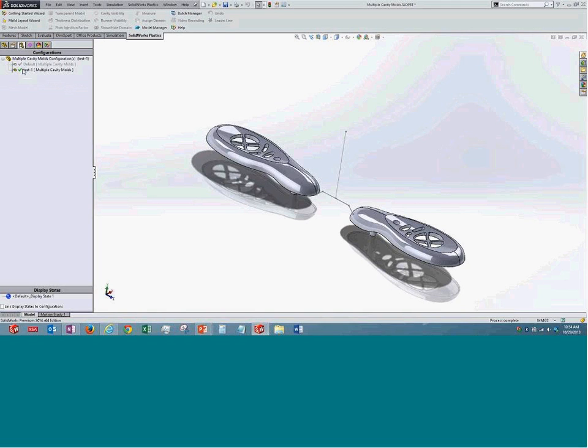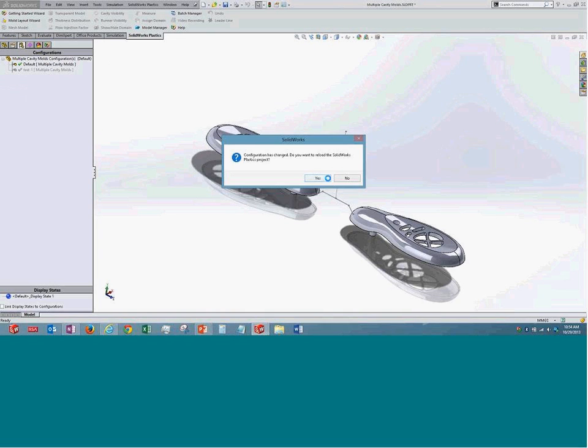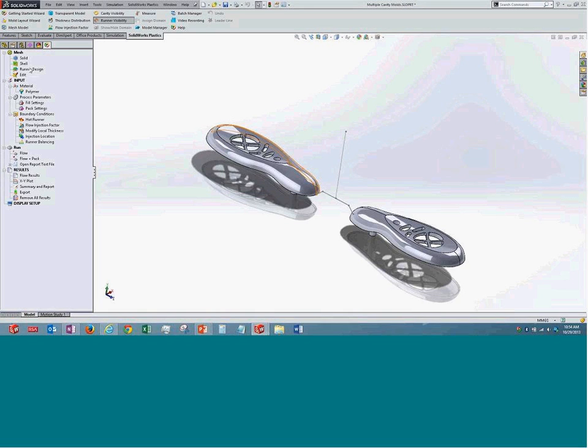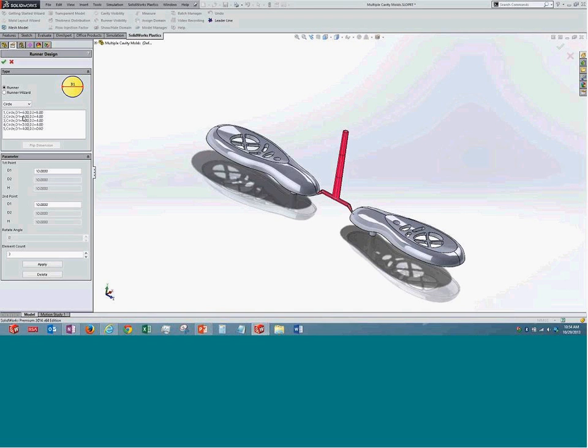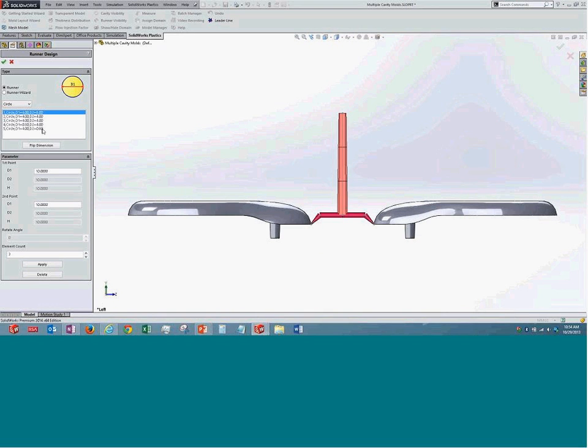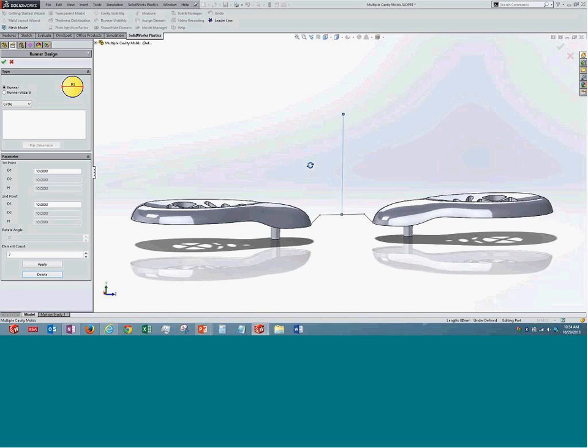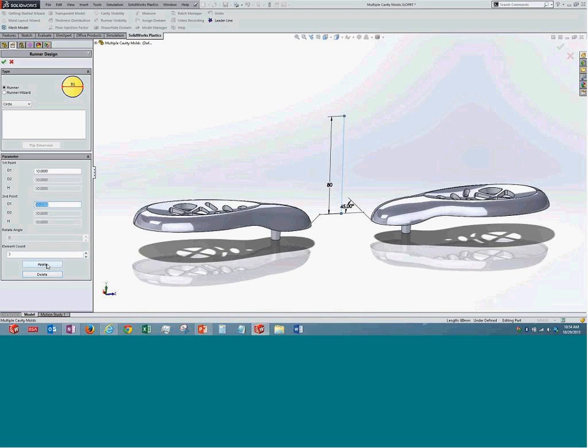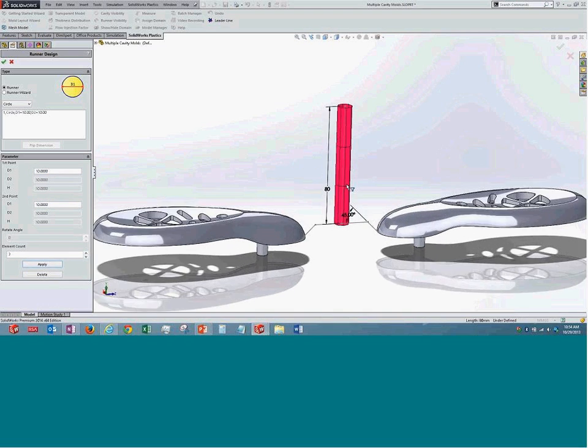So if you see the way it has been created, I just select that particular sketch, dimensions over here, and apply. That's it. So the runner is created. I can give different dimensions over here. I can give six of those different runners. A set of ready-made options are available, so we can do that. There are different types of runners and input gate systems.